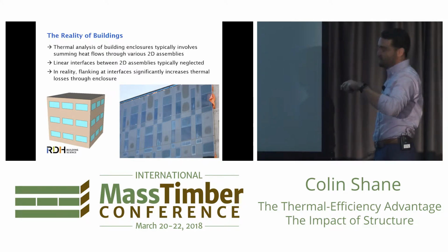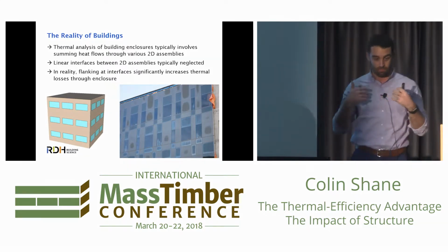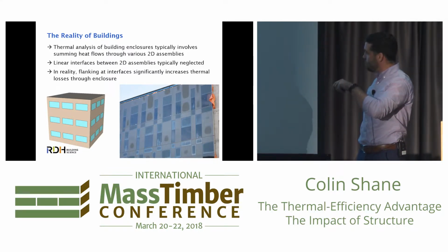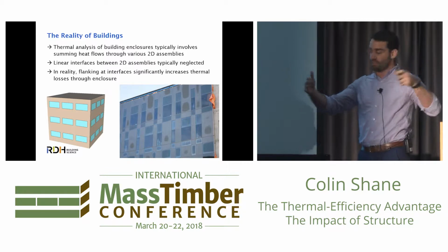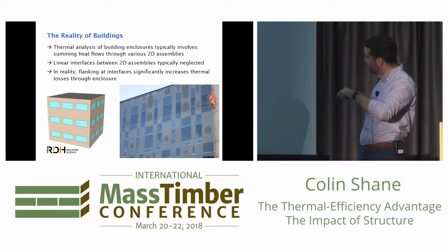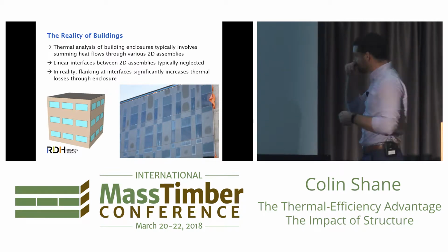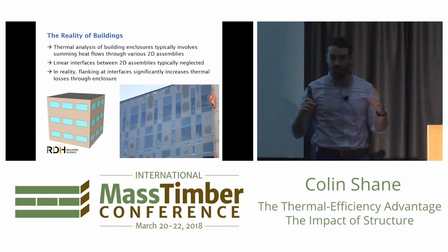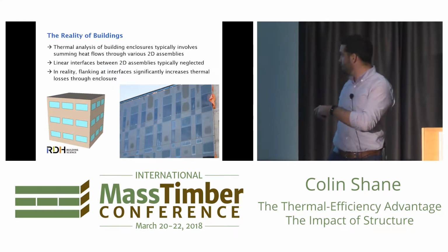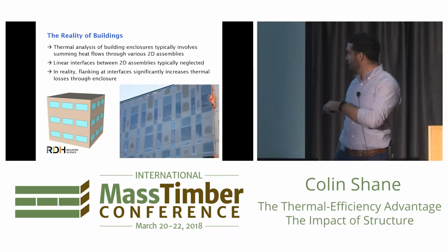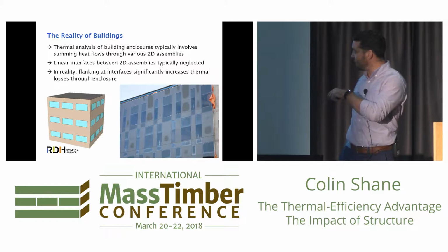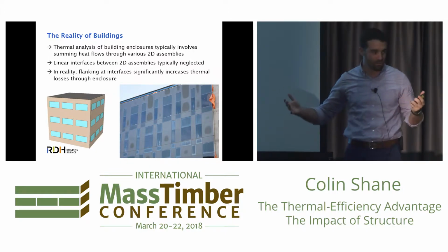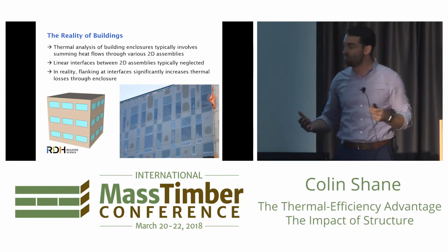There's a lot of insulation in the middle of the panel that's very continuous. There's no steel members or anything like that poking through it. But we have aluminum mullions from the curtain wall bypassing that insulation around the edges, and there's a whole bunch of heat flow, a ring of heat flow around the perimeter of the spandrel unit. So we could put R20 insulation, for instance, inside the middle of that spandrel panel, and when we look at it in more than a single section cut, and we account for the thermal losses flanking around the perimeter, that very commonly goes down into the range of R5 to R8. Cuts it well more than in half, right?